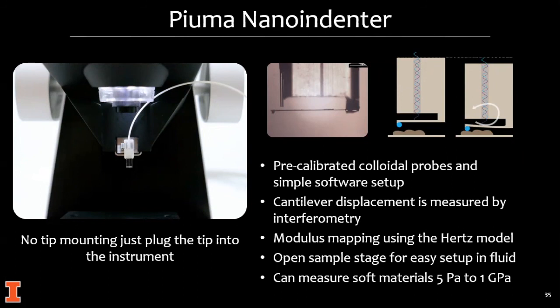One more question here. Can you comment on how to calibrate these tiny forces with the tip? I understand the question here. Calibrations are pretty much what I showed you in the beginning. If you are aiming to get less than 1 nanonewton of force, that's coming into play not from the calibration, it's coming into choosing the really soft cantilevers that can be sensitive to forces that low without damaging your sample.